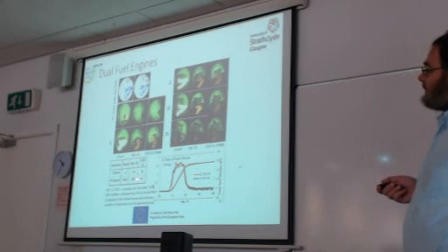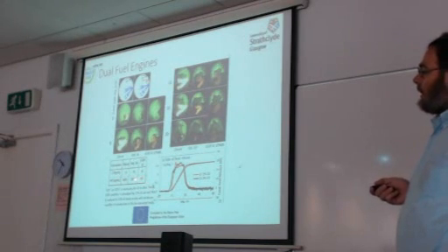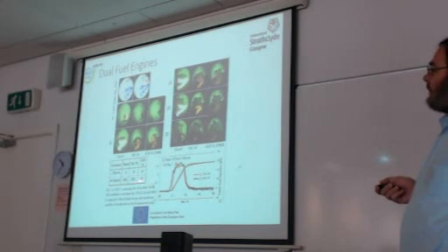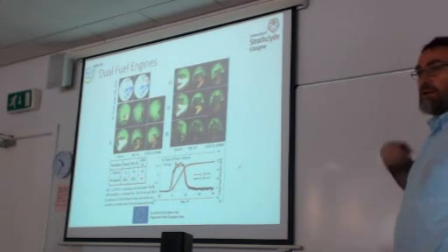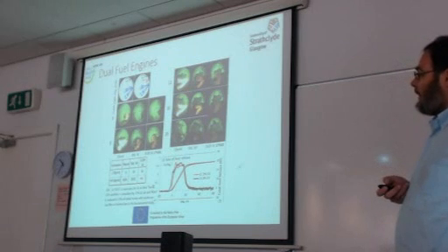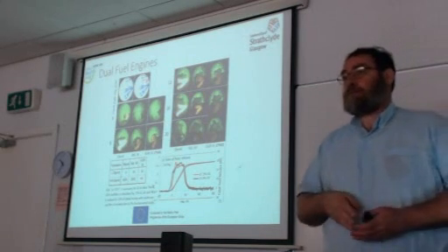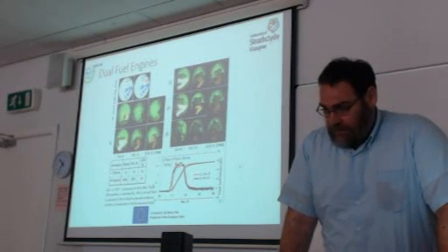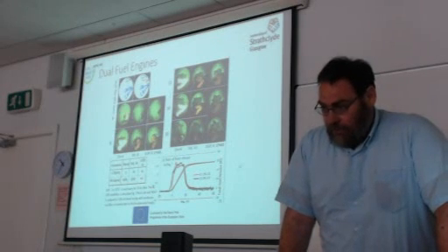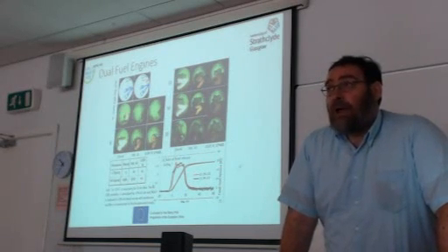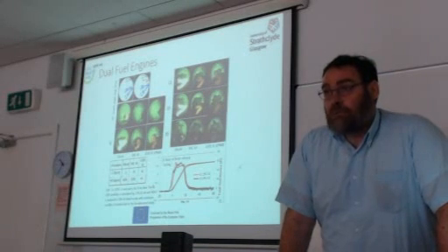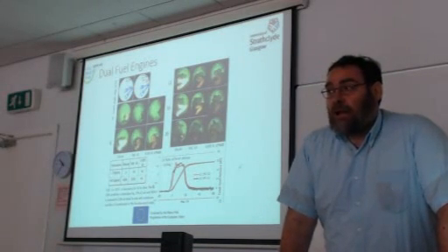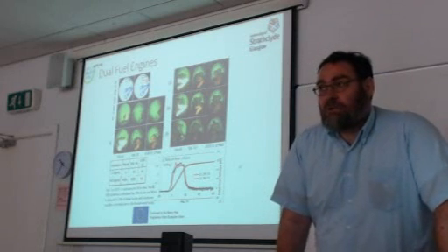So you can see here that NOx standard in ppm, parts per million. In the standard diesel engine it is 500 ppm for this specific case. For the standard gas ignition, the NOx was reduced to 300 ppm, and by using EGR, NOx further reduced down to 44 ppm. So that actually reduces NOx. Does this concept affect the efficiency of the engine?